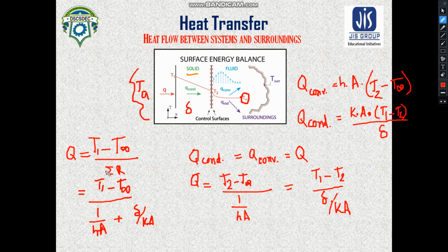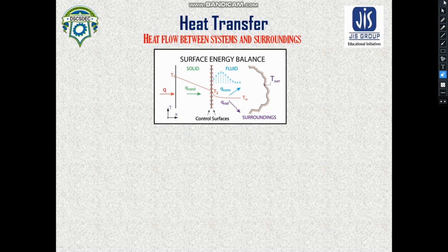Now heat is being resisted because of the two modes, the conduction and convection. So you need to add up the thermal resistances because of this conduction as well as convection. If you add it up, then you will find the rate of heat transfer. So this is not any problem, I believe. With this understanding of the combined conduction and convection problem, let us take some problem.